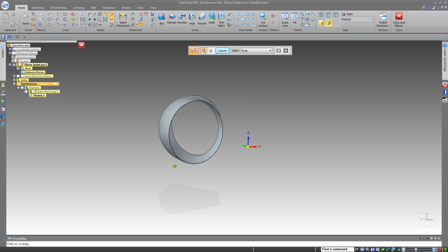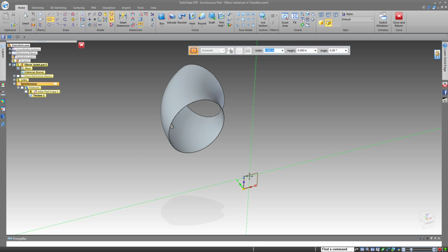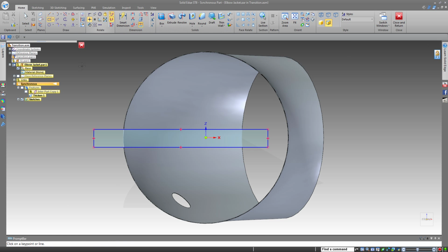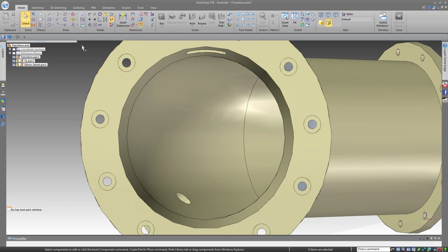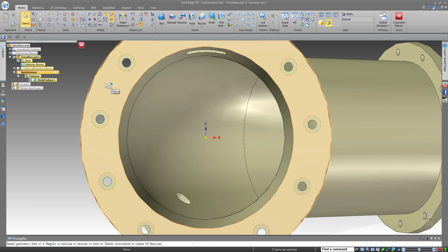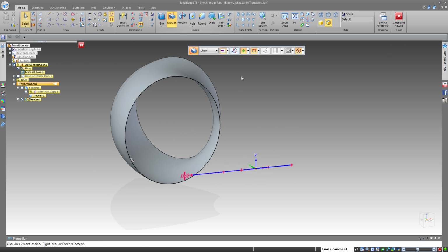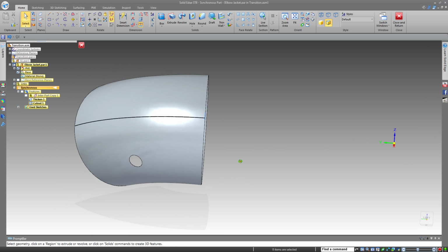And of course we need to split it down the edge here. So again, we'll do just a little sketch like we did originally. And then let's make sure that's on the center. We'll put a relationship here to tie that to the center. There we go. And 0.0325 is the same gap as I did on the outside. Oops. Close it again. Habit. I'm closing that. All right. Extrude cut that all the way through. All right. So the seam is the same as the other one.